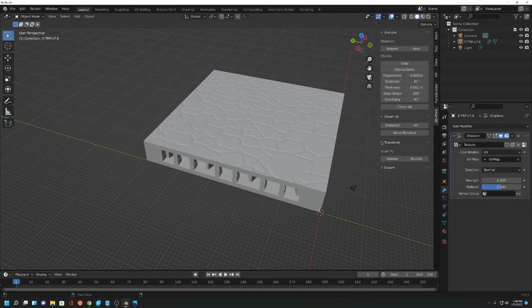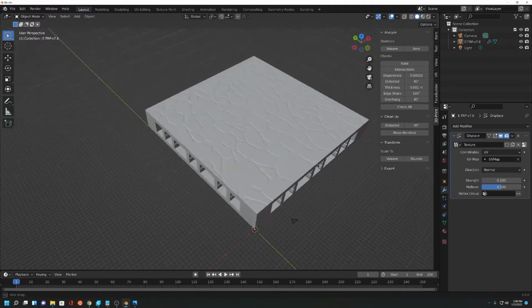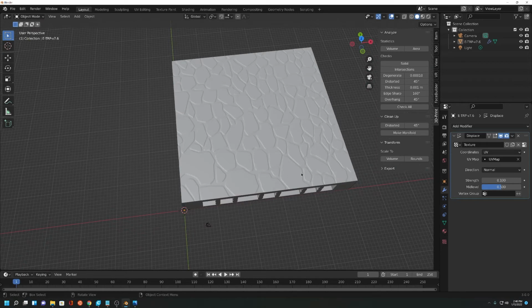Now, what this allows you to do is make sure that the current mesh that you have will work with 3D printing, whether it's resin or FDM. So we're going to first click Check All. We're going to check volume, area, solidity, and intersections to make sure that this is capable of 3D printing. It will automatically correct those upon doing it. So let's just hit Check All. You got the little icon going, and pretty soon it'll be dropping right here on the bottom.